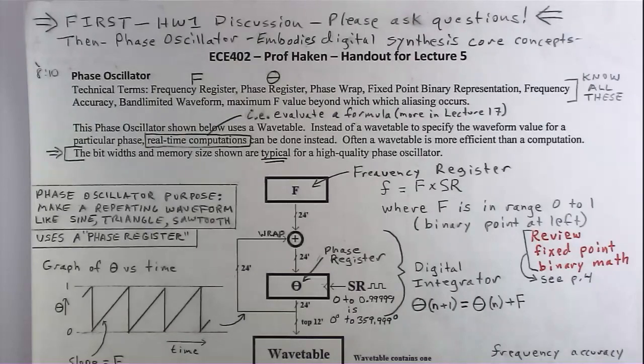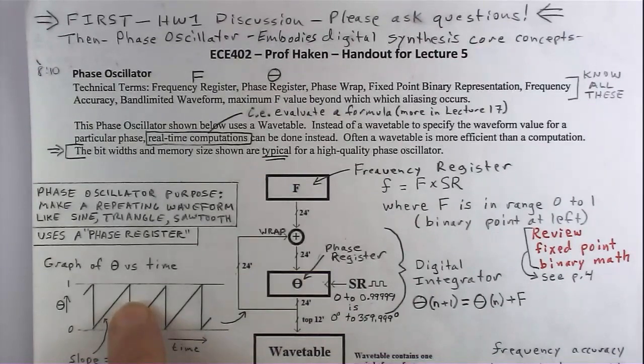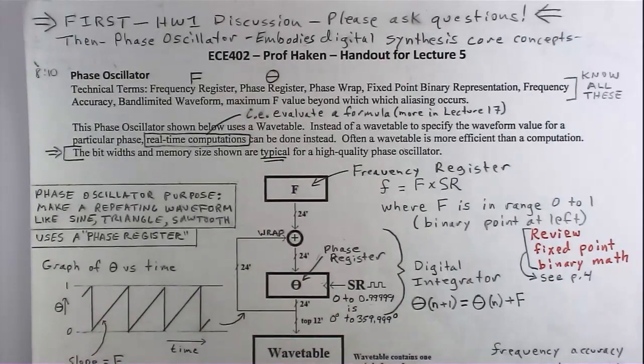Well, a sawtooth has an infinite number of harmonics, right? Here's a real sawtooth, a sort of perfect sawtooth in the analog world, not in the digital world. It would look like this. It has, which tells you from Fourier theory, you need loads and loads of sine waves to make sharp corners. In the digital world, you better never see a sharp corner like that. If you're going to synthesize it and you've got sharp corners, then you're fooling yourself. It's not what it looks like, right?